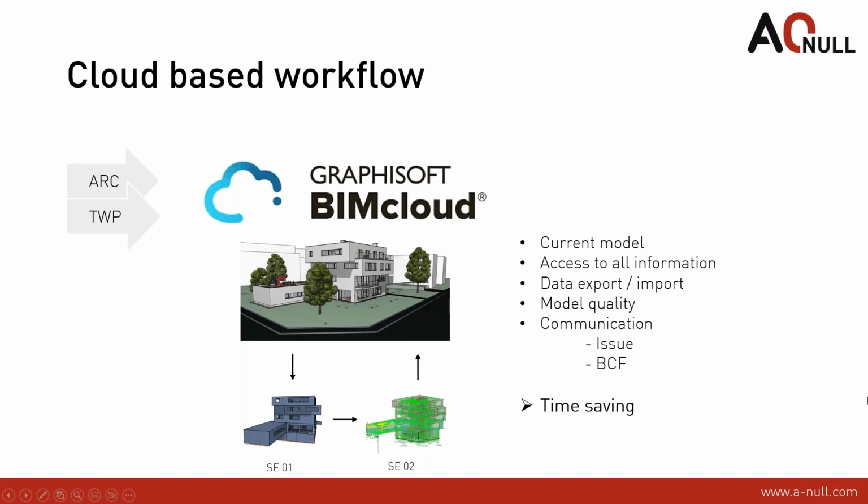For Archicad, from Graphisoft, there is the BIM Cloud. It's like this: the whole BIM model in Archicad is on the BIM Cloud. And then you can, as a civil engineer, go into the model and improve it, give your feedback in the Archicad model, and then you can save the analytical model from the BIM Cloud, make the calculations in RFEM, and give the information back.